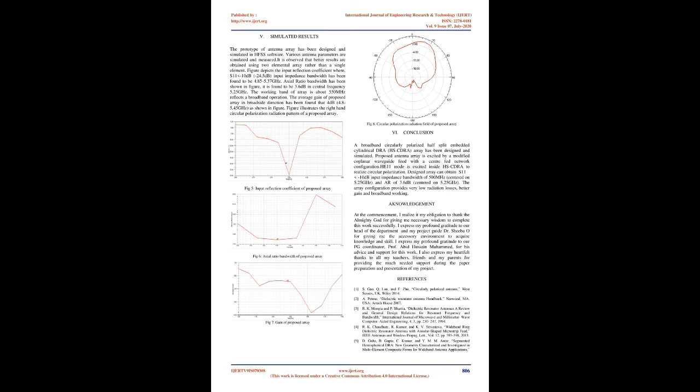4. Structural analysis. A. Effect of embedded structure. Fig. 3 shows the effect of embedded structure on input reflection coefficient and axial ratio. The input reflection coefficient decreases with the embedded structure, a DRA with lower permittivity inserted in the groove of a DRA with higher permittivity. This is due to the coupling between DRAs. The value of axial ratio, below 6 dB, reflects that the embedded structure generates circular polarization. Input reflection coefficient, embedded DRA. Input reflection coefficient, slotted patch. Axial ratio bandwidth, single DRA.